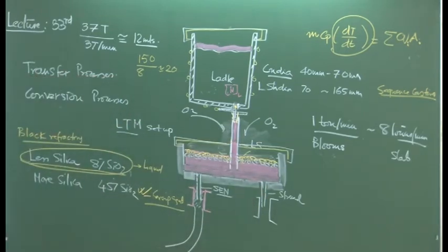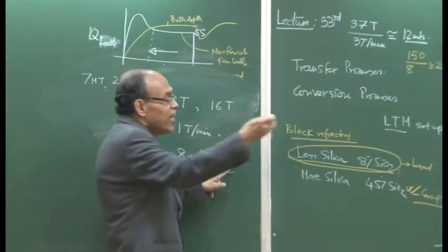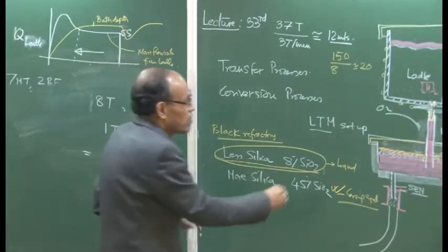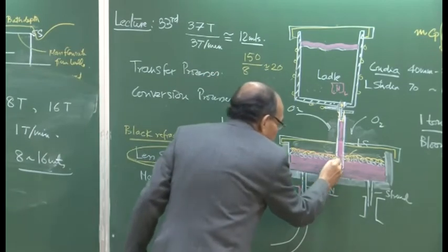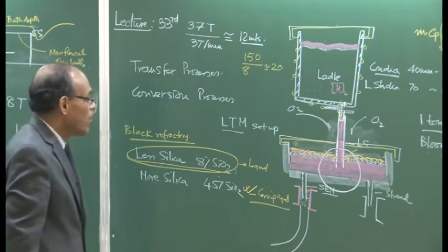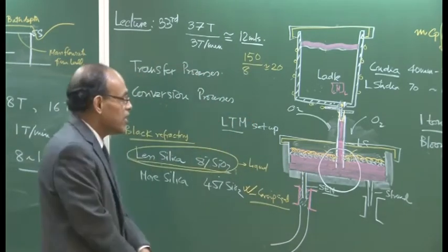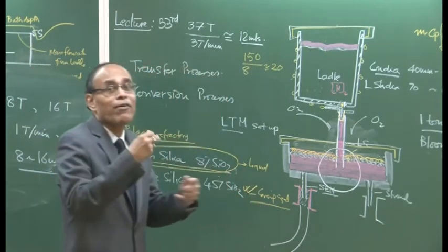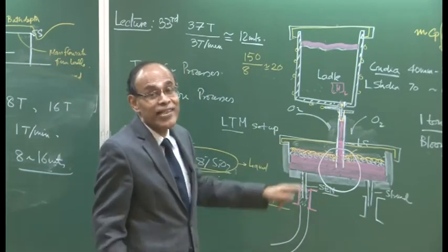This farthest strand possibly does not see any motion of steel except for the drainage action as the molten metal is going out. The churning action, the high turbulence region, is restricted mostly in and around the shroud region itself, but far away from the ladle shroud region elsewhere the bath is pretty much stagnant. I would not say stagnant, but very slowly moving.